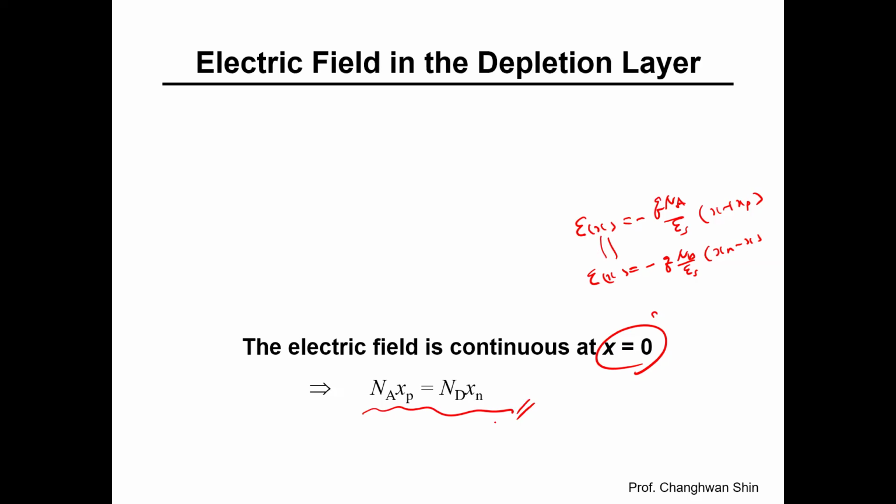It is like two countries establishing a demilitarized zone between them. The smaller country, the more heavily doped region, gives up less territory than the larger country, the lightly doped region. For instance, if the N side has 100 times the doping concentration of the P side, then the depletion region on the P side will be 100 times larger than on the N side.